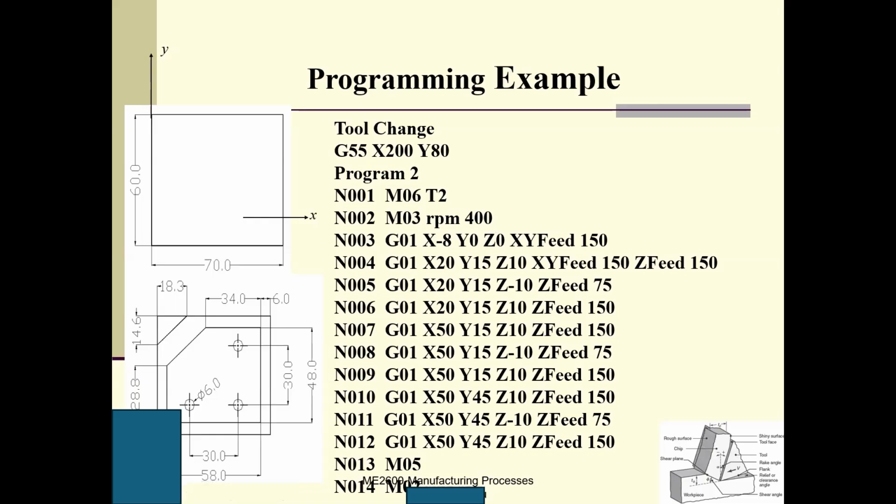What? We change the RPM mid cut. It's like on one of the lines, you would change the RPM on it, would that work to change it while it's cutting? Yeah, you can change the RPM. Yeah, you can. But usually here we just specify the RPM. And RPM does not change here, but we change the speed. And Z is the feed.